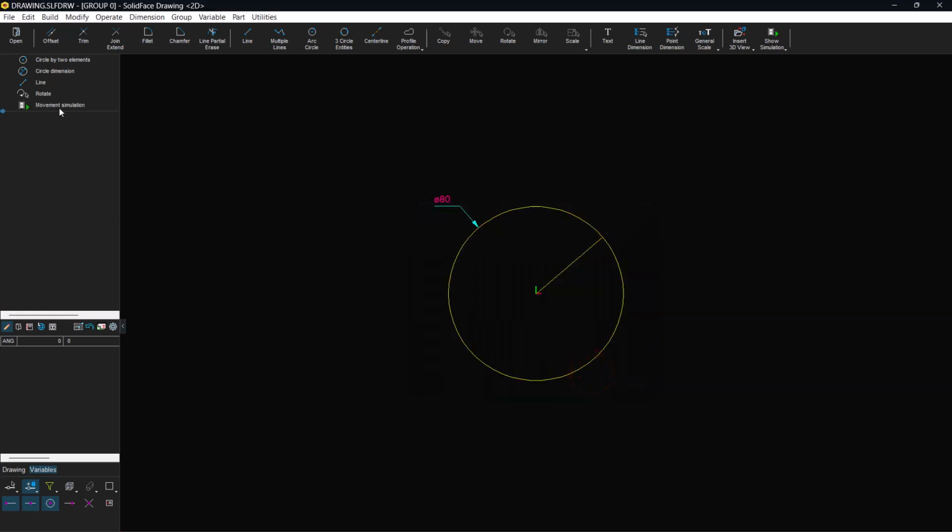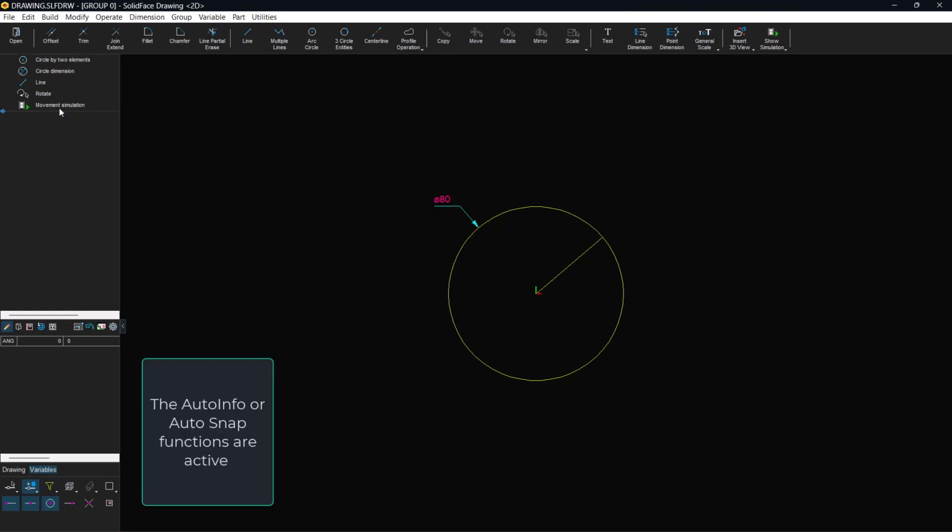Note that the simulation command was stored at the end of the list. You can reposition it to the bottom of the list if you wish. This is not necessary because the simulation button searches for a saved simulation command and runs the process.